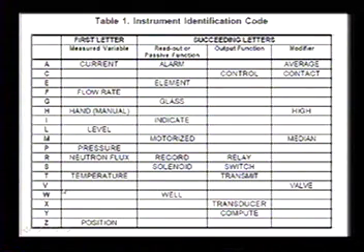See how this works? And V is valve, W is well, like a thermal well, X is transducer, Y is compute, and Z is position. So if you have a ZCO, that's a common thing. That's a position closed, or sometimes you see an SYZ. It all depends on the different companies what they want that to mean.